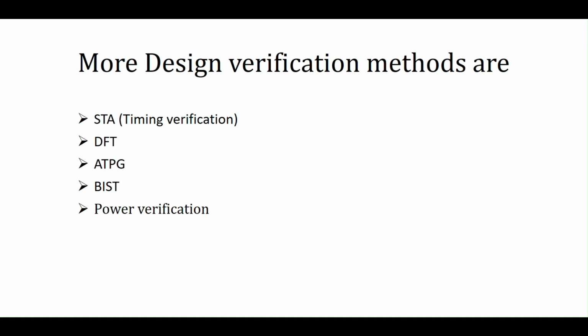There are more design verification methods such as static timing analysis for timing verification, then design for testability. Then we have ATPG, which is automatic test pattern generation. Other than that, we have BIST, which is built-in self-test, and power verification. All these methods require different tools. We can perform STA in OpenSTA, and DFT and ATPG need commercial tools like Cadence and Synopsys.